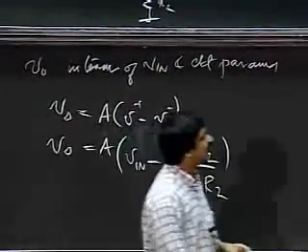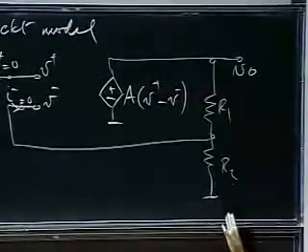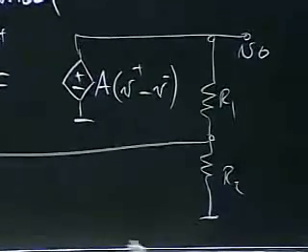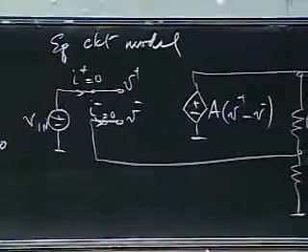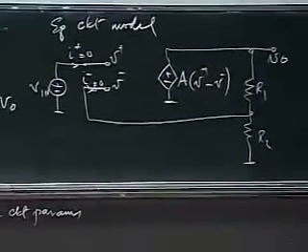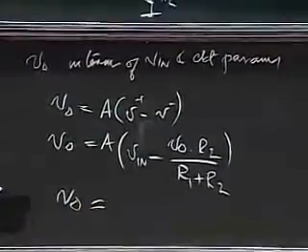Okay, just stare at that for another second. The voltage at this node here is simply given by the resistive divider because no current is flowing in this direction. And no current flows in because I'm telling you there's no current there, based on my abstraction. I'm telling you I minus is 0. So that voltage is simply the voltage at this resistive divider. And so I can simplify it further and write this as V naught.